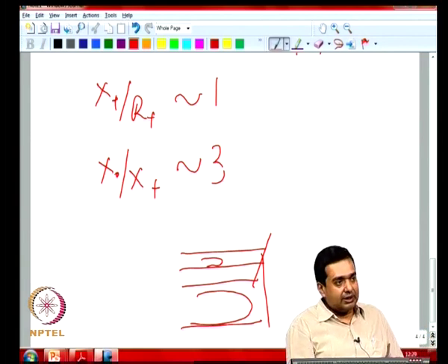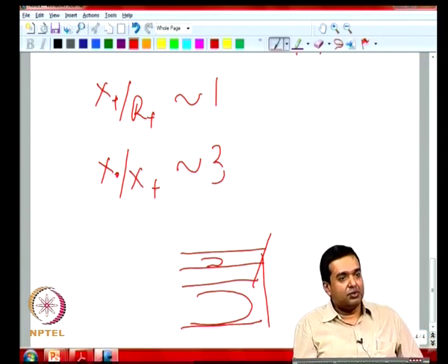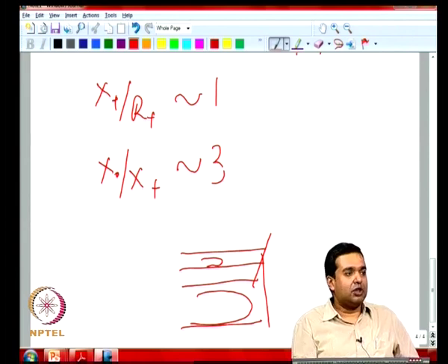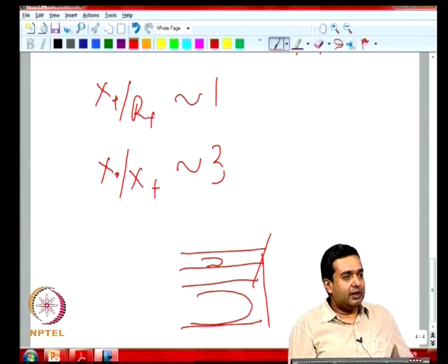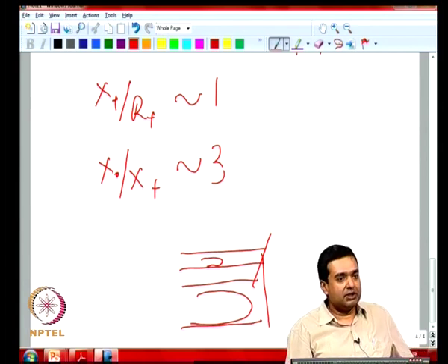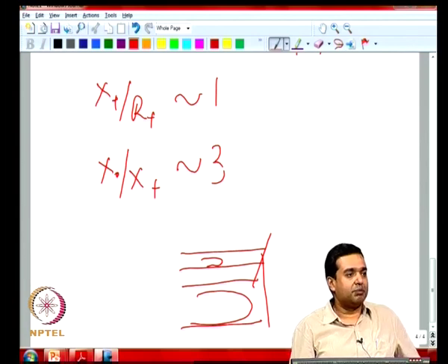So, if you look at the power quality that you would see in an urban system, you would see lower voltage drops along the line, whereas often in a village you might encounter that the lights are not glowing brightly, it is quite dim. It is because the physical line is situated so far away, and the impedance of that entire line is causing larger voltage drops when people are drawing power. Okay.